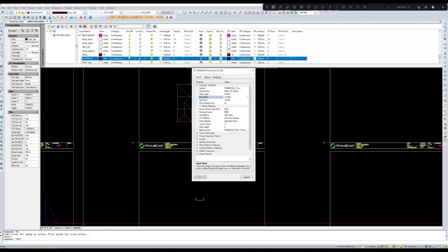Roof slope is 15 degree. Reduce level 6500. Truss spacing 1200. First arm 900. Again for jack, this we keep as it is default. Ceiling tiles, let it be default. Let all of them be default. Load, we have already defined.